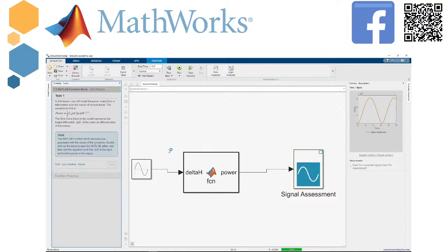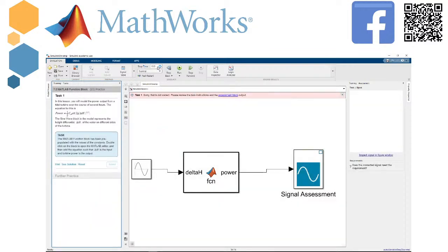Double click here. Now it's 0. Switch to 0.25. Press OK. Note that the icon changes. Indeed, it changed, and as you can see here, it's discrete, no longer continuous. Now we need to connect it to the signal assessment. As you see here, the sine is no longer continuous; it's discrete, and as you can see, there are little steps.